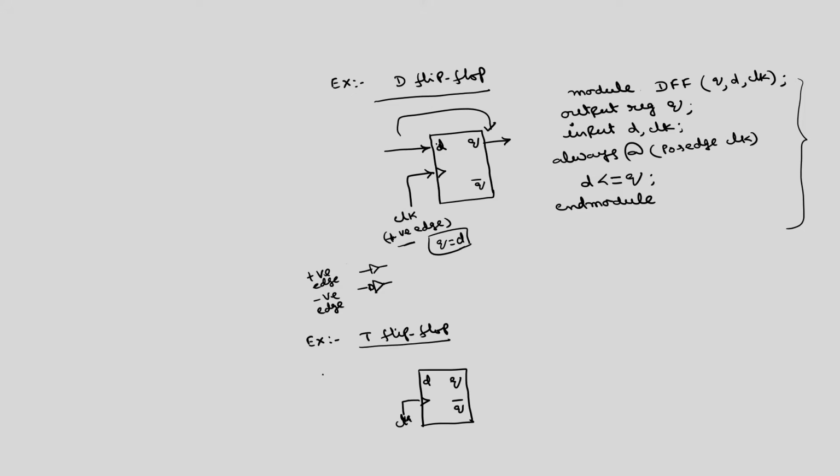So, I have to use some conversion logic here. With input T overall, the output should be D. This can be a function of Q also. This combinational logic is basically a function of T and Q.